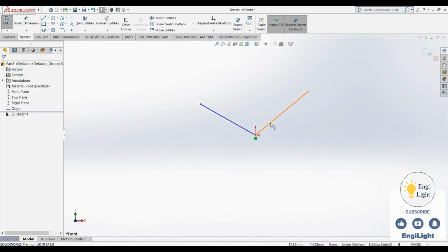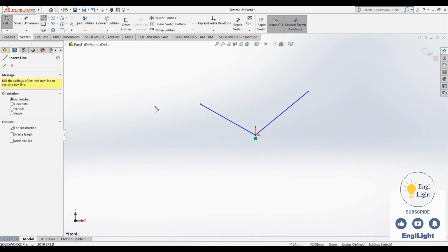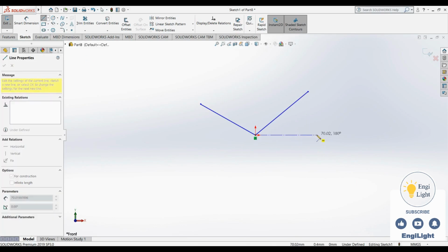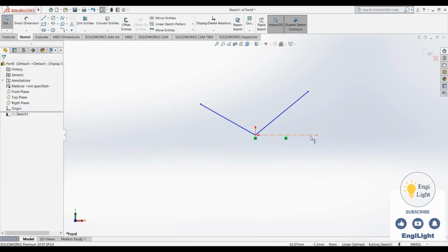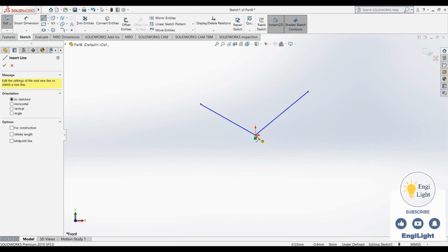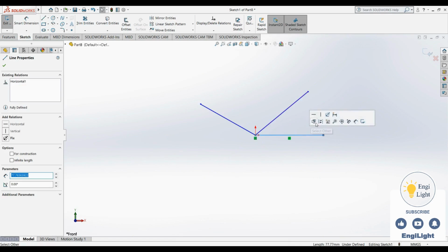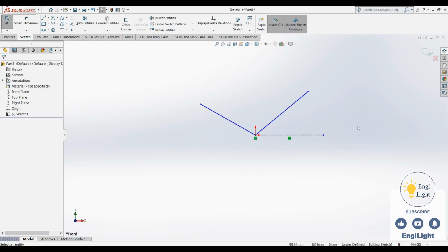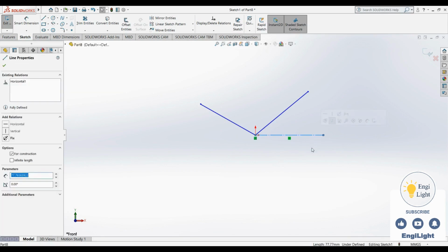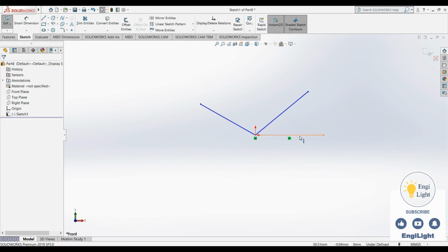Here, this line segment should form a 45-degree angle with the horizontal. So, I draw a center line here as a reference. I can also do something else to create a center line. I can simply use the Line tool to draw a regular line. Then click on the line and use this command to convert it into a center line or a construction line. Alternatively, I press Ctrl+Z to revert it to a regular line.